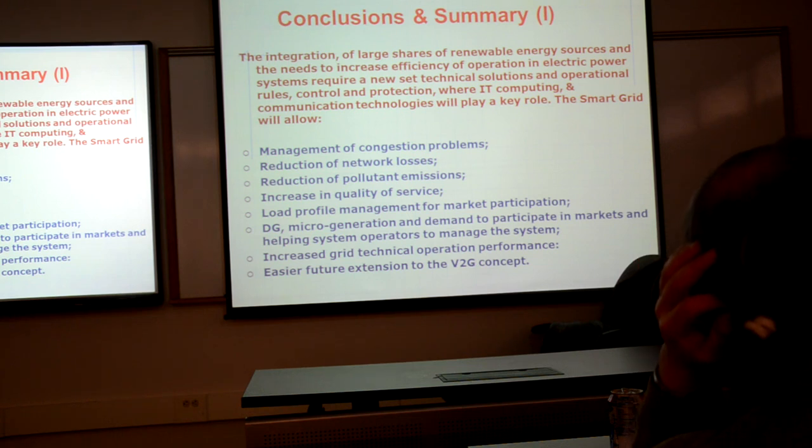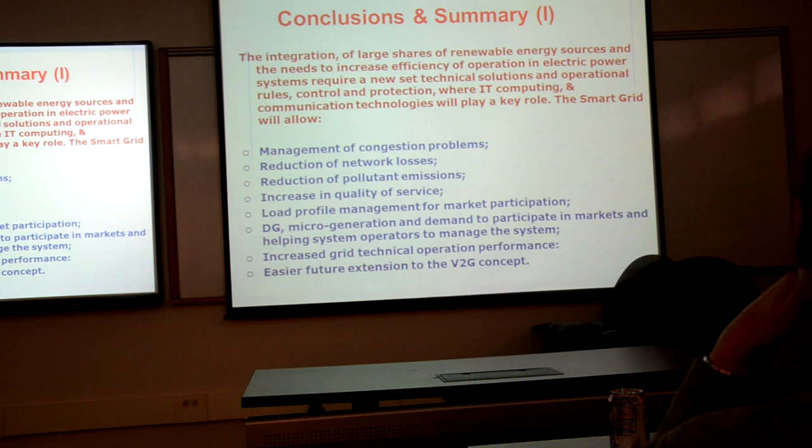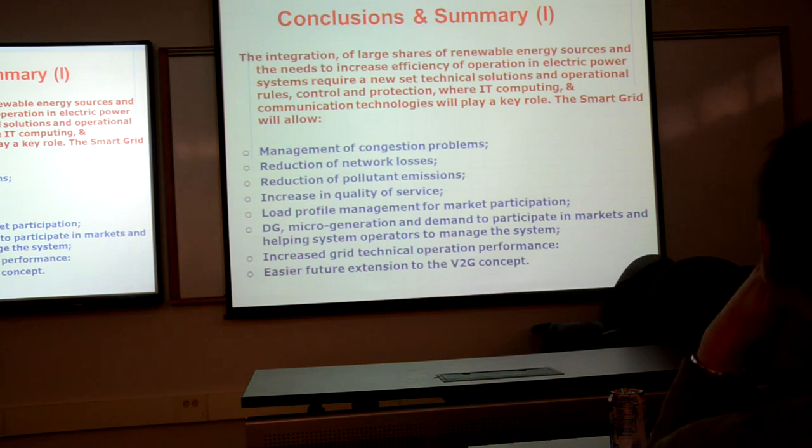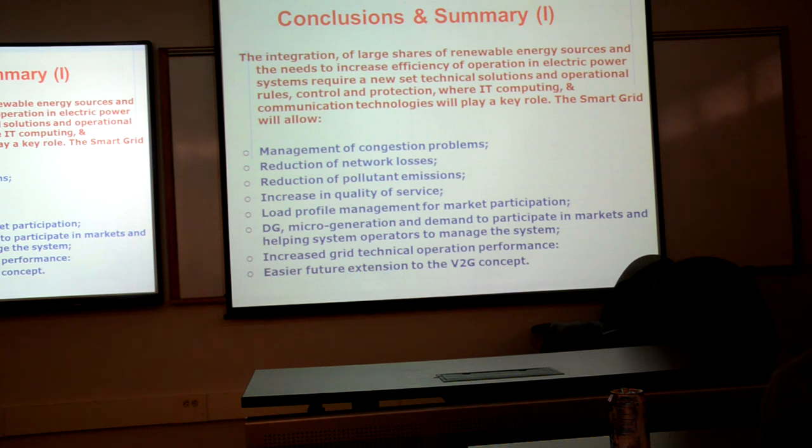Usually you track, for example, the ratio between the resistance and the reactance of the line to see if you have a short circuit or not. That is feasible for a transmission line with a much larger time of response than the microgrid, which needs a much shorter time of response, and you don't have such a tracking system of the ratio between the resistance and the reactance of the transmission line. So those are the issues that we have.